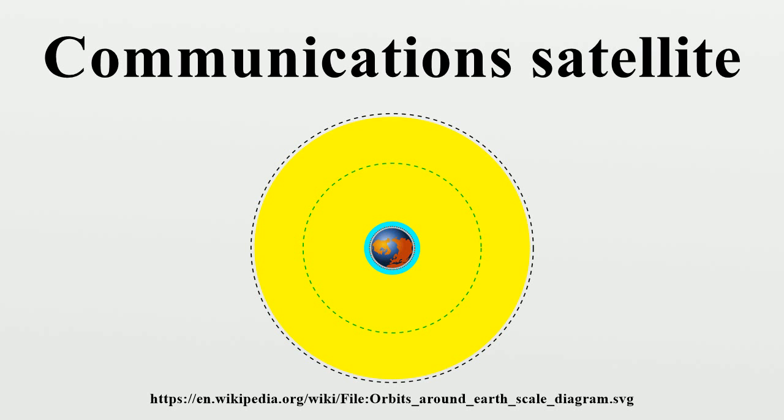There are two major classes of communications satellites, passive and active. Passive satellites only reflect the signal coming from the source toward the direction of the receiver. With passive satellites, the reflected signal is not amplified at the satellite, and only a very small amount of the transmitted energy reflects toward the receiver. Since the satellite is so far above Earth, the radio signal is attenuated on its long journey due to free space path loss, so the signal received on Earth is very weak.